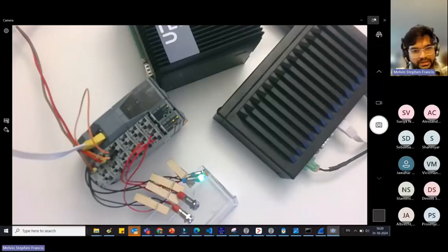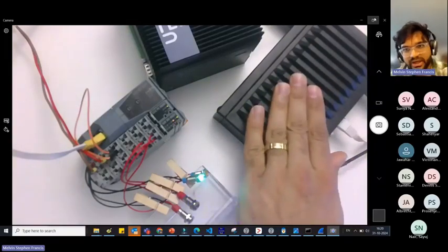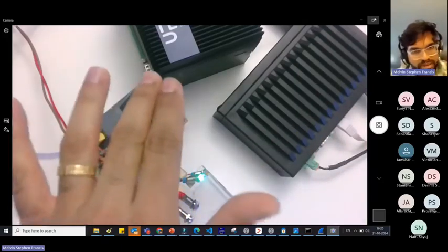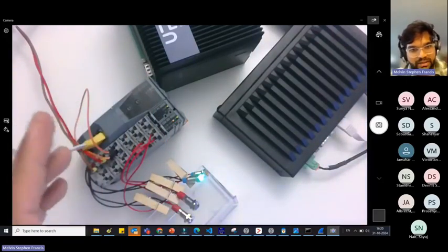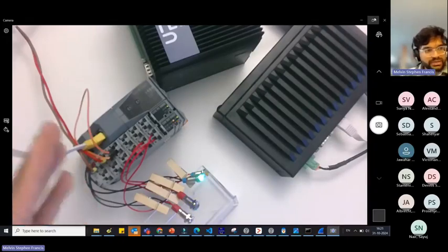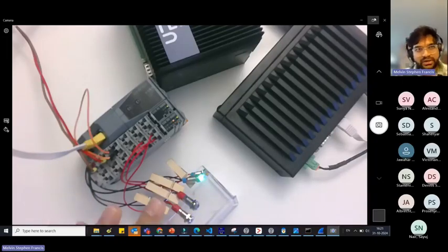So this is the overall application to show that we are able to send a packet every 1 ms, and we are toggling these LEDs. This particular board is running the OPC UA FX TSN SDK, and this is from B&R, Bernecker and Rainer. It's an Austrian-based company who have support for OPC UA FX for this particular IO module. We also have a Qt GUI that controls the speed of the LED.